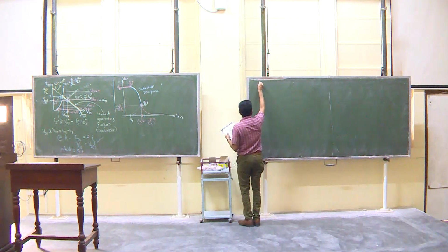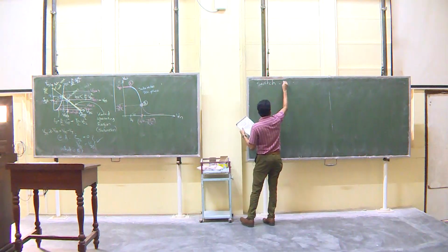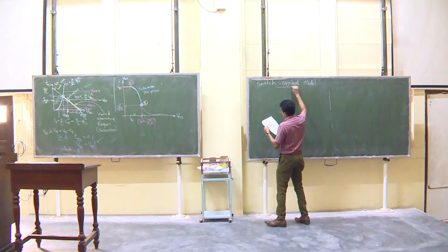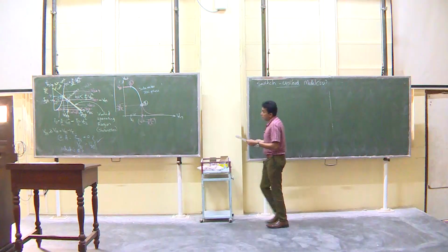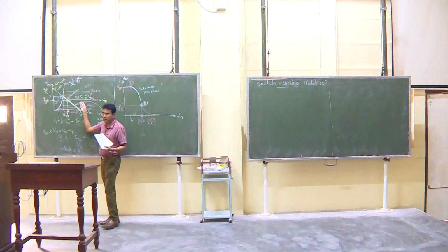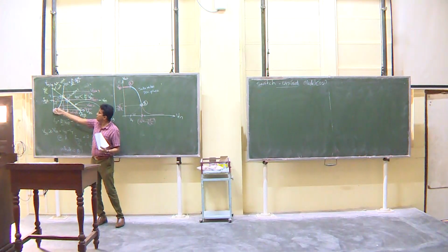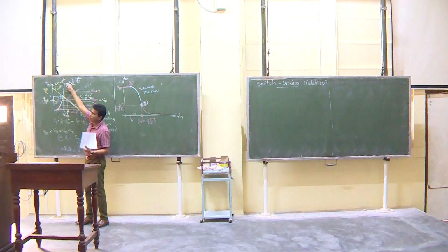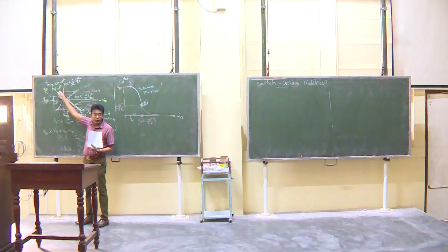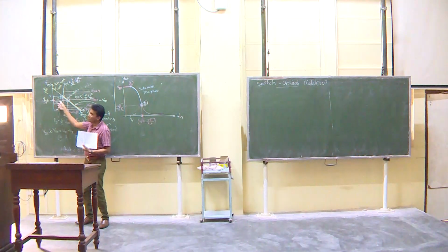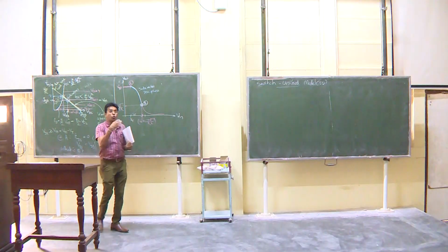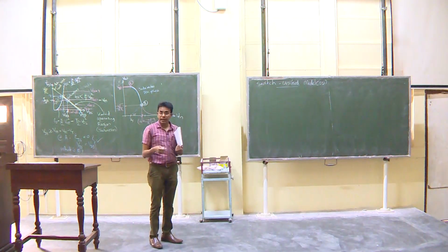This is the next model, switch unified, SU model. Now, in this figure, it has some parts missing. In the triode region, you don't have any curves. Earlier you had a triode like a straight line, resistor kind of thing. But even that is not here, no? We haven't drawn that here. So, in this model, we are kind of ignoring this. We are avoiding that from going into that region. But what if it goes? Then we need to know how it behaves in that region as well.